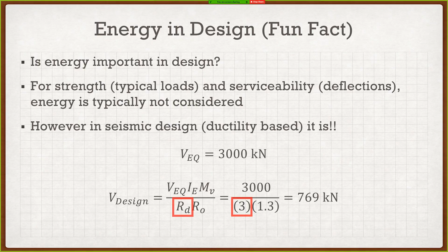That's why if we're testing a shear wall in the lab, we'll build the shear wall for the first story of the structure, test that, and say, all right, if this one's good to go, then the shear for the rest of the building will, of course, also be good to go as well.